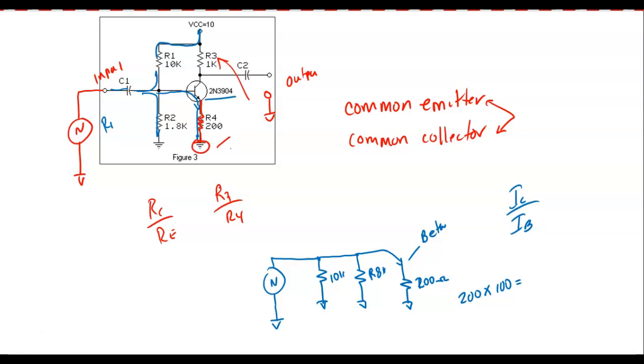We know beta's got a problem, right? Using beta anytime on transistors has a problem. Why is that? Why is using beta in a math formula got problems? Why do we have to use minimum beta? Because if I looked at the beta on a 3904, it can be anywhere between 30 and 300. Yeah, because of the span. You're right. And so what we do on this one is definitely an approximation of trying to figure out what we call the input resistance of the amplifier.